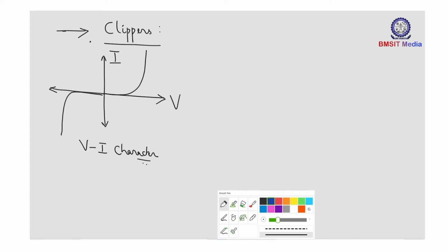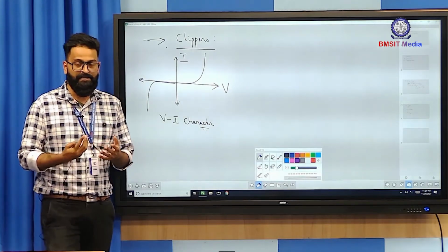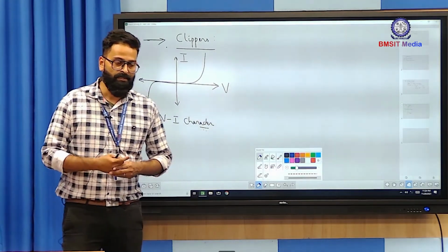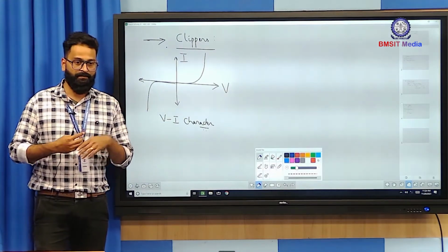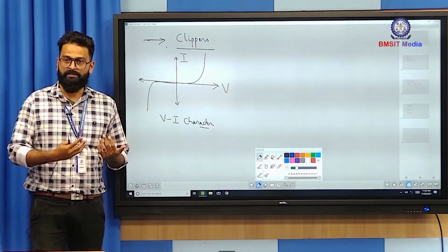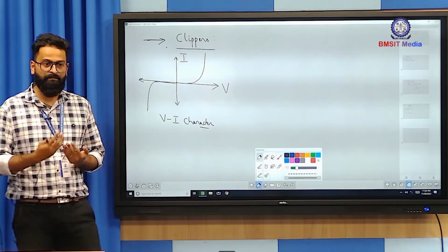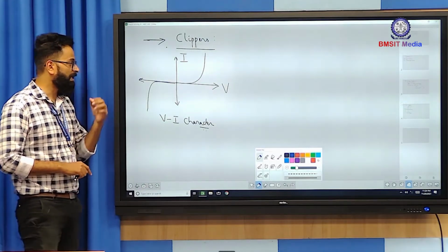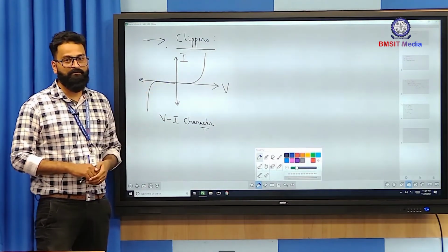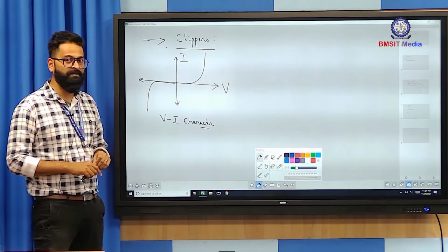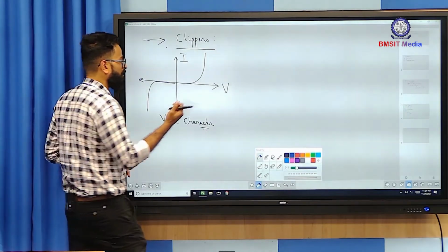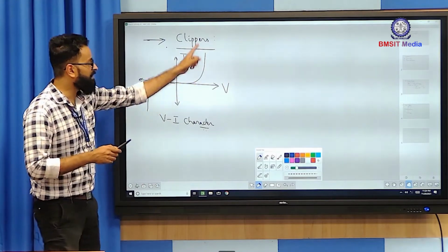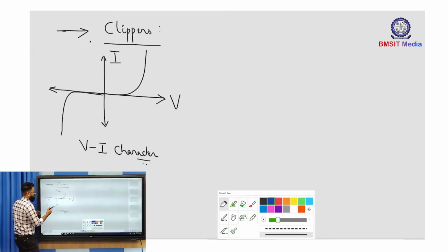Now, a diode is basically a semiconductor material. To a semiconductor material, we cannot apply Ohm's law. But while doing circuit analysis, we predominantly use Ohm's law, Kirchhoff's voltage law, Kirchhoff's current law, etc. So firstly, we have to obtain a linear model for the diode. To obtain the linear model of the diode, we look into the linear region of the diode. From the p-n junction characteristics, it is observed that